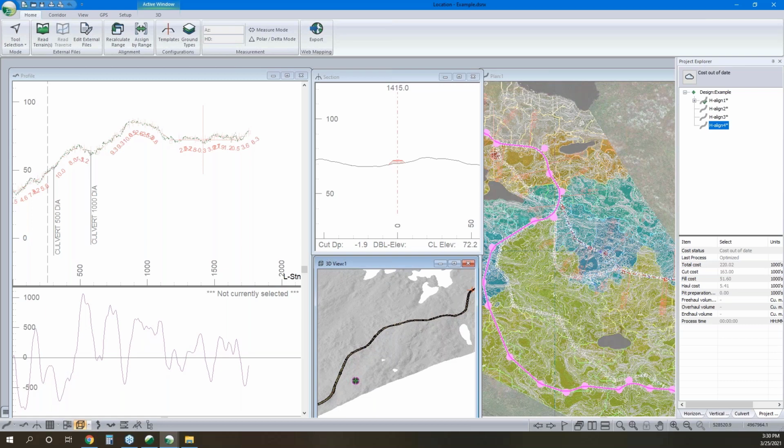Occasionally, even if you have not great accuracy limitations in the overall survey for the data, if you're looking at things on a more local level, a lot of the time those accuracy limitations are an overall bias for the area, so you can improve things by just shifting your data set up or down an appropriate amount. But that's ultimately up to the designer to make that call.